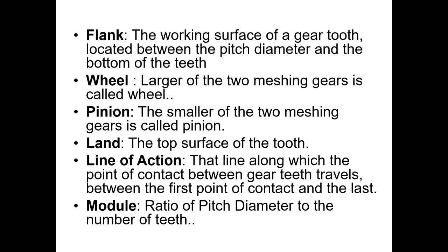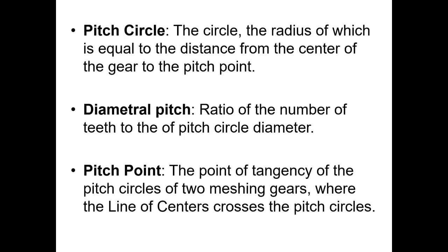Next, the line of action: that line along which the point of contact between gear teeth travels between the first point of contact and the last. Next, module: ratio of pitch diameter to the number of teeth. Next, let's look at pitch circle, diametral pitch, and then pitch point.